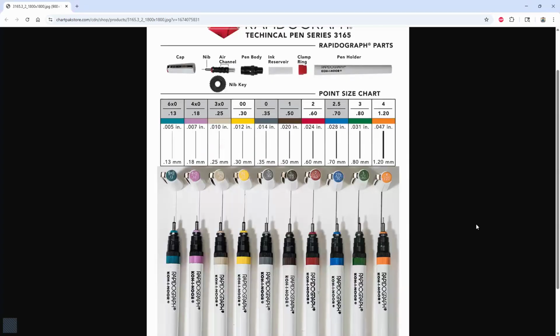So you can see where this concept is coming from. So just giving you that little bit of history so you know where the thinking is in terms of this concept of colors equals a line thickness. And if you want, you can borrow these line thicknesses and use these exactly. And then if you want to make some modifications, like let's say you start with a 0.35, you don't like it as well as you would like it to be, the thickness on it, you can change it to 0.32 to 0.34, anything you want. So that nice fine tuning is available in AutoCAD.